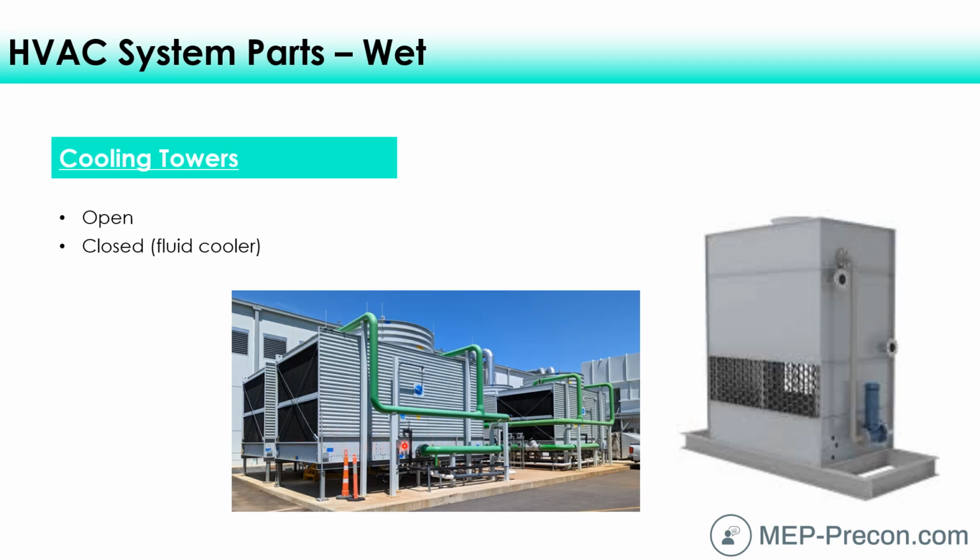Not only that, but as this water evaporates, what happens when water evaporates? What do you typically see on your shower after years and years of operation if you don't wipe it down after every use? It tends to build up those hard water deposits, right? Kind of that cloudy scale that's really, really hard to remove. And that's the same thing within this piping system and within the heat exchanger of your chiller. So as the water evaporates and the water becomes more and more hard, the hard water deposits that are left, usually from calcium, is what the hardness comes from.